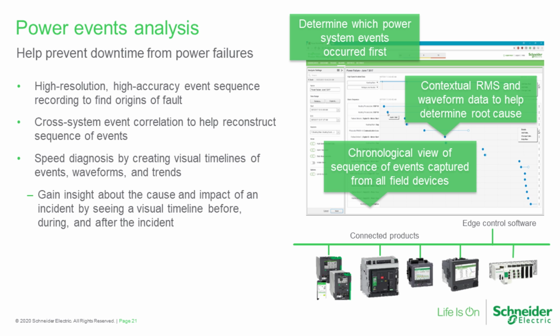And if something goes wrong, tracking those events in a sequential, orderly manner is hugely important. So sequence of events reporting with some good analysis tools really helps you prevent future outages, right? So for example, arranging the events in a timeline so an operator can quickly assess what happened, right?